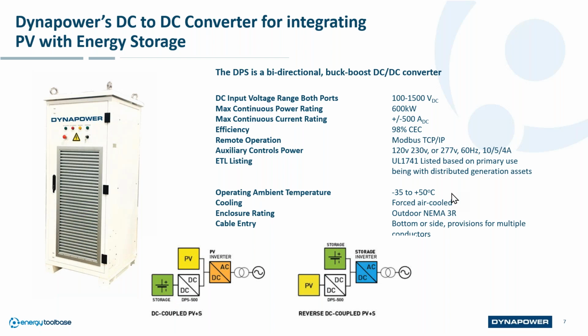But that inverter has the dynamic transfer capability. It can operate either on or off grid. So there you have kind of like the best of all worlds. If resiliency is one of the requirements, that's the way to go. If it's not, then you can go with the other configuration showing the PV inverter as the AC supply to the grid. So that's about it for me. Tracy, I guess Kevin's going to take it.